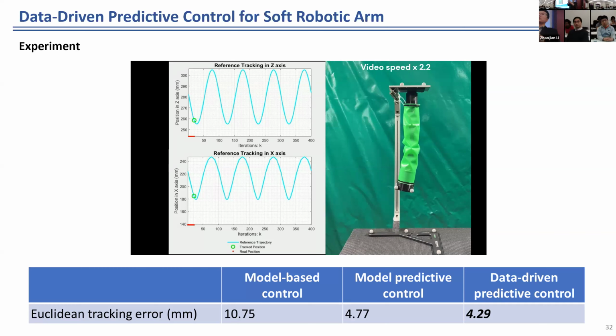First of all, if you look at the claw or the soft fingers, it typically is electric driven, so you have to place the motors, which makes the whole end effector really heavy. That slows down the system, and durability can also be a problem. The beauty of the vacuum system is that the end effector is so light. It's just a soft cup, and you can move around, and we can also do really good control of the vacuum system. And it's also really cost effective. So all things considered, we think that vacuum is the best way to go for fruit picking.